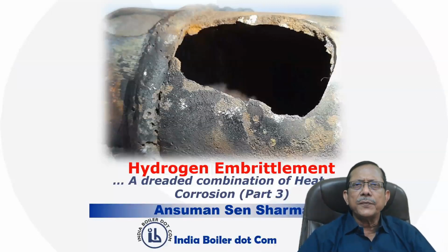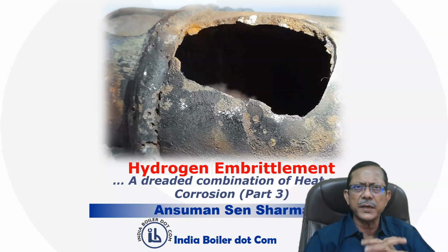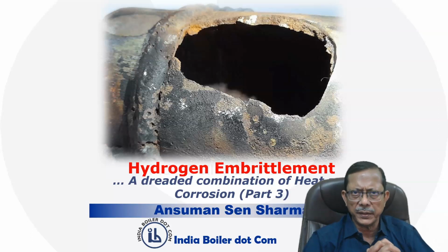In the last video, I discussed the findings on this particular case, right? Identification of the root cause, and there we have seen that this hydrogen embrittlement, which is confirmed, was occurring because of two parts of the problem. One is the corrosion problem, which was primarily because of caustic gouging corrosion that we have seen, and since there was an overheating prevailing in the system, in the furnace area, particularly towards the rear water wall, that is how the hydrogen embrittlement failures were occurring in this particular industry.